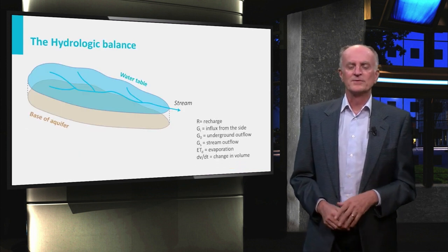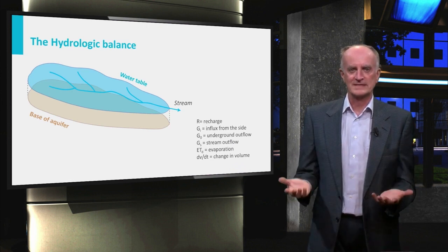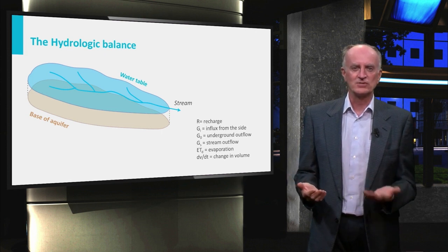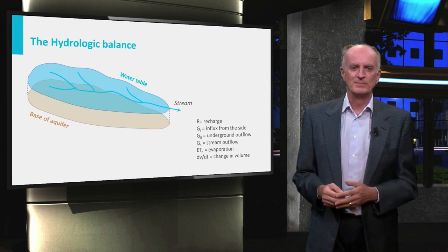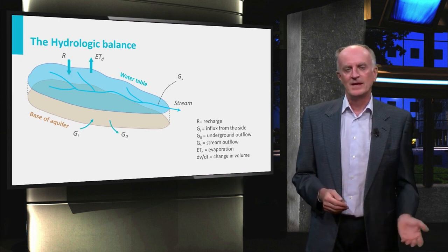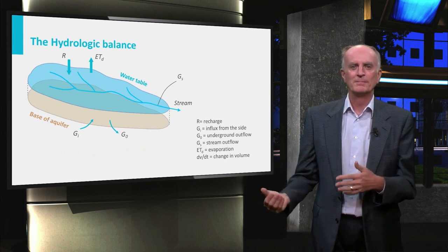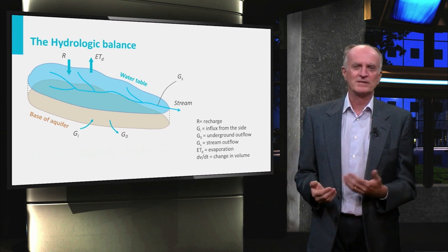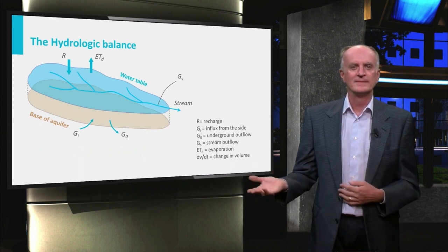Already from these first few slides, you see that hydrogeology has a lot to do with flow and fluxes. A quantitative knowledge of such fluxes is a necessity for geologists and hydrogeologists. And I want to give you here a very few basic ideas. Fluxes of water into, through, and out of the aquifer are combined into the hydrogeological balance, which is essentially conservation of mass applied to water. What comes in has to go out.